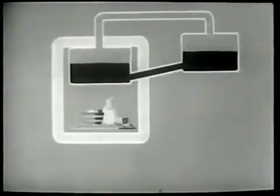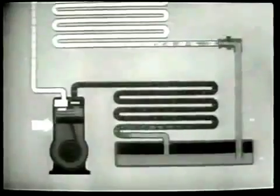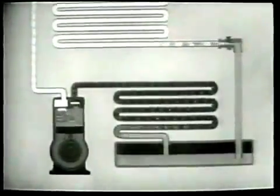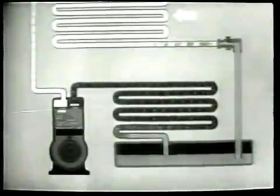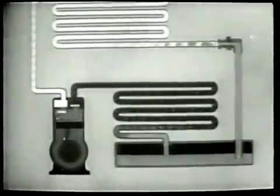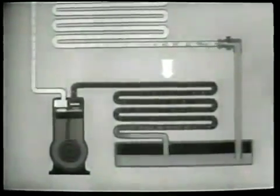With the introduction of a refrigerator box insulated against outside heat, the elements of refrigeration are ready to be brought together in a refrigeration cycle. In the compression cycle, the compressor forces the refrigerant through the system. The liquid refrigerant in the cooling unit absorbs heat, thereby cooling its surroundings, and changes to a gas. The gaseous refrigerant loses this heat in the condenser and changes back to a liquid.